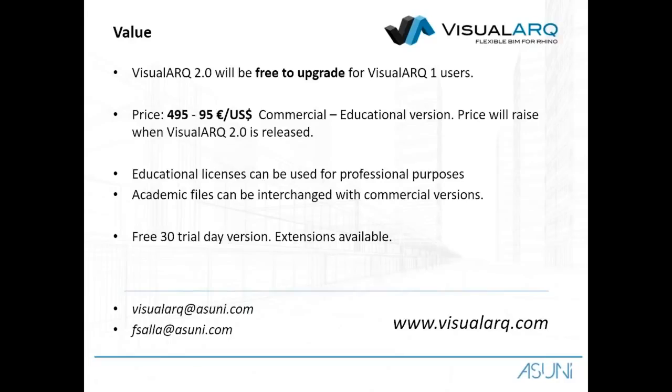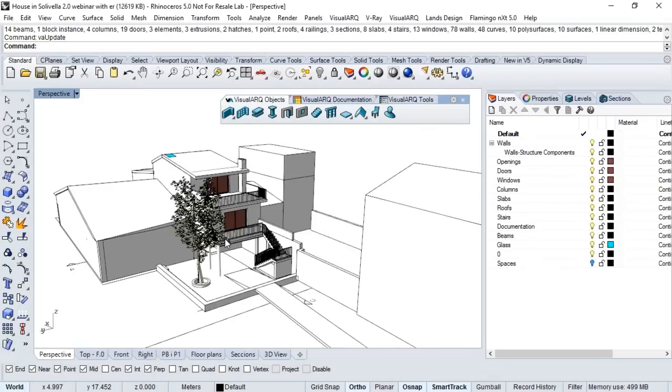Okay, so let's take a look at the new features live with an example model. Taking a look at the toolbar, we can see that in the VisualARQ objects, we have added these two new objects, the furniture and the elements. They work in a very similar way. Under the documentation toolbar, we have added the annotation object and these two new icons for the edit levels, for the level manager and for the section manager. Okay, now we will see how they work.